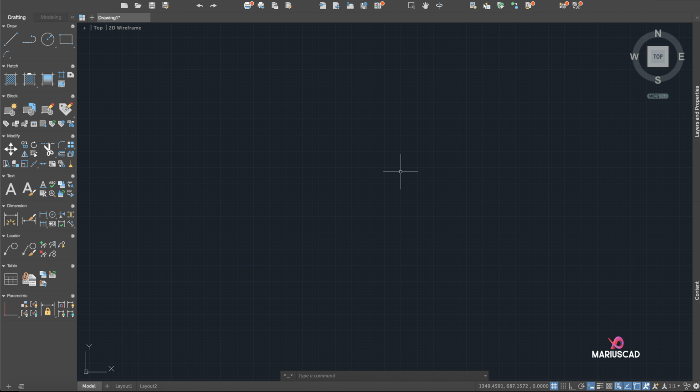After that we have the drawing area where you can draw everything you need. After that we have the command bar. You can write line here, or you can write L, it is the same, or you can write in every corner of the drawing area, for example here or here, it is absolutely the same thing. After that we have the status bar toggle, exactly here, where you can find some details, some commands for